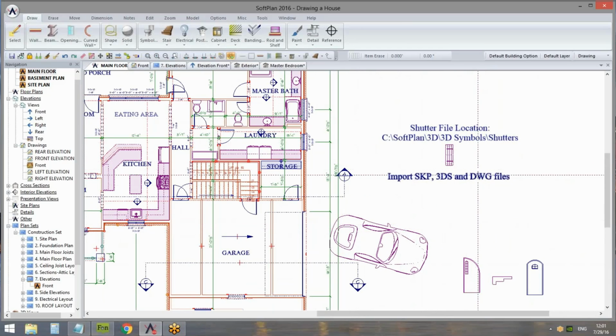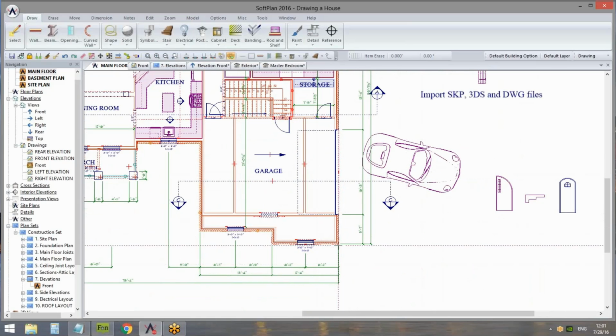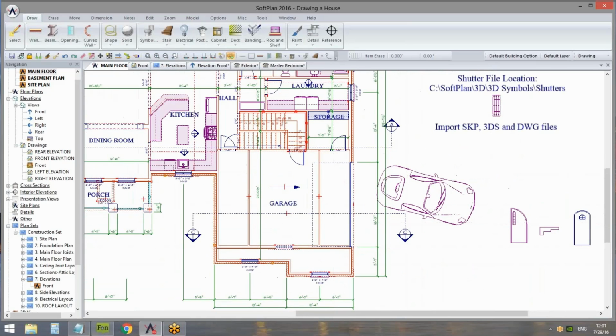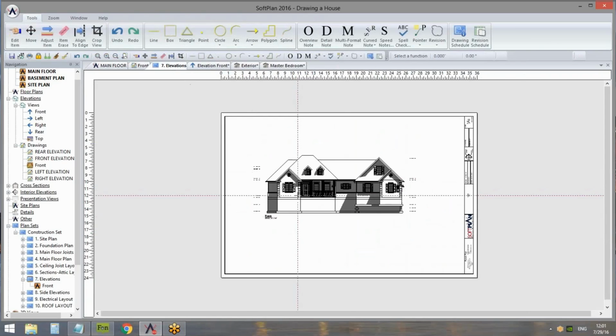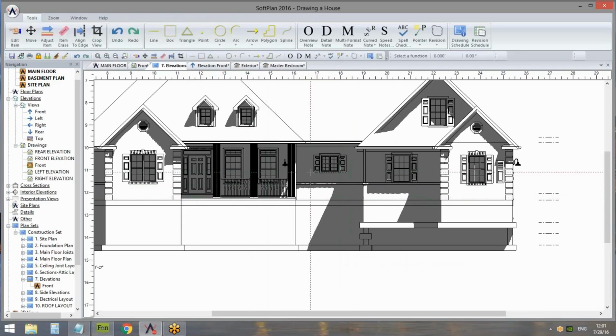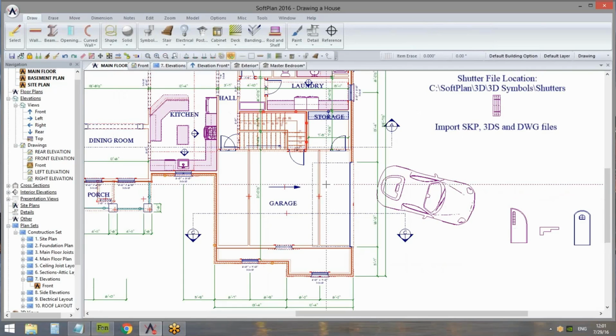And I'd also gotten a question about importing shutters just to use them as false shutters if you were going to draw them as a symbol onto your floor plan. And we'll also be going through creating tray ceilings and about adjusting the print pen for shadow paint when you go to save an elevation, because initially it may come up a little dark and it may obscure some other parts of the elevation. So for instance, the windows, or just obscure other details so they're not as prominent. So we'll be going through that as well.